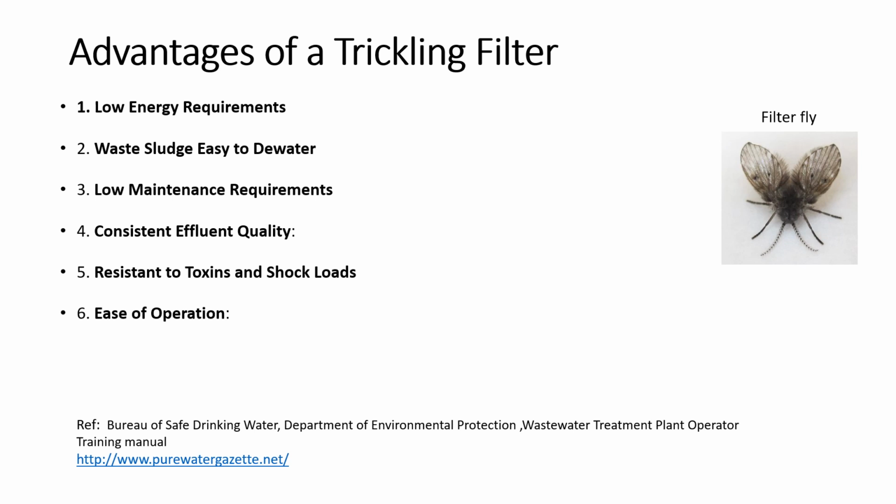And low maintenance requirements is only required for the trickling filter. Since there are very limited number of moving parts, there is very low maintenance of the equipments. Consistent effluent quality, that is trickling filters perform extremely reliably at low and consistent loadings.